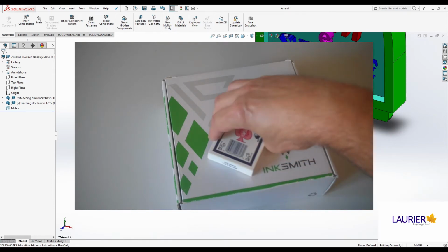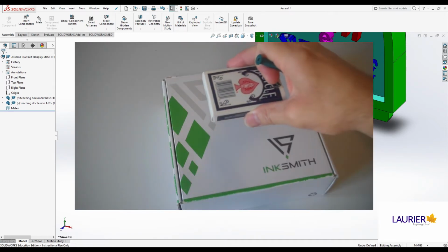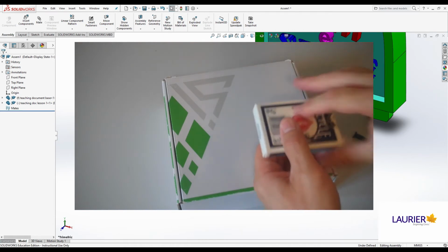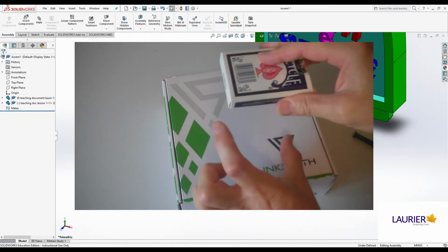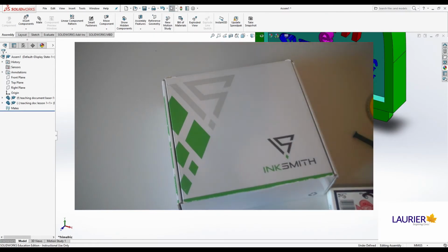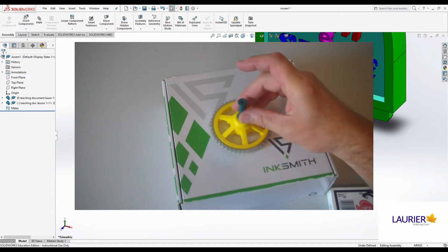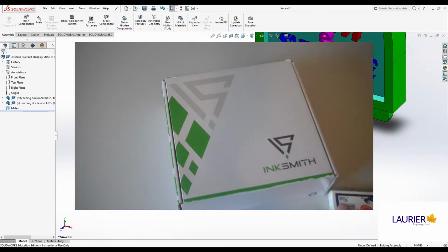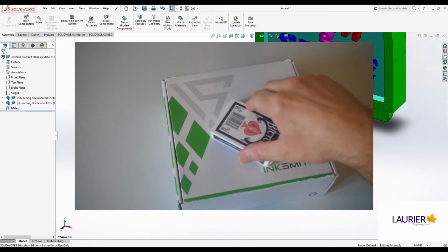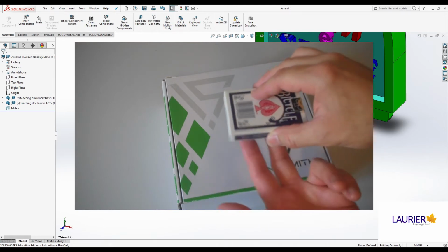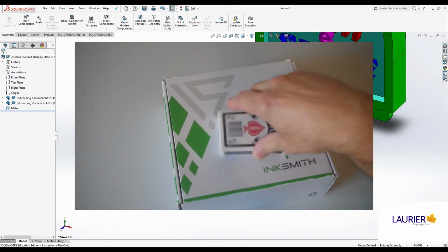The most common is the coincident mate, which means that the two entities must be touching. There's also a distance mate, which sets a set distance between them. If we use the latter for a plane-to-plane mate, one face will be on one plane, and the other face will be on a parallel plane, a set distance from that first plane. The next most common mate that we'll use is a concentric mate. In a concentric mate, cylindrical features are positioned such that they are coaxial to one another. Back to our plane-to-plane coincident mate. This mate moves the parts along an axis normal to the planes of the selected faces, so that these faces are now coplanar.